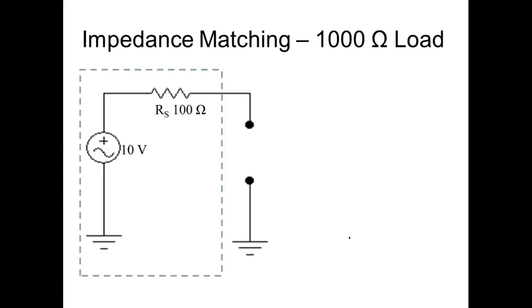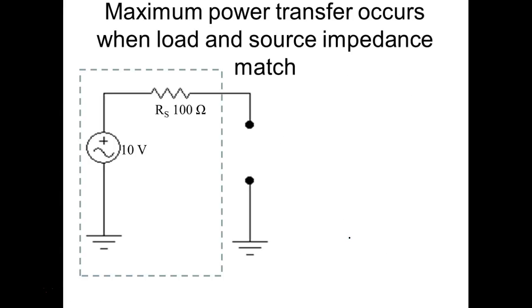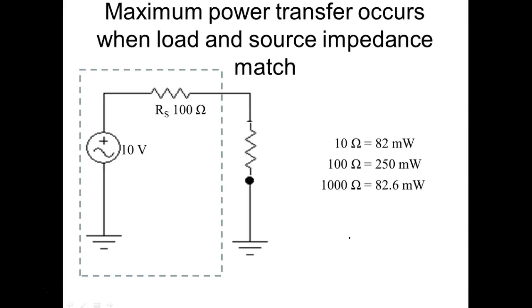So what we do is we set up cables. Coaxial cables and twisted pair cables have a certain impedance. And if my transmitter has that impedance, and my receiver has that impedance, and the cable has that impedance, we get maximum power transfer between the transmitter and the receiver. Everything matches. And this is true only in communications, though. In communications, we don't arbitrarily choose these conductors.